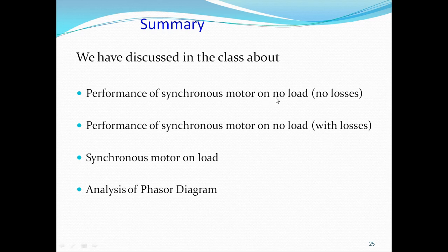In the vector diagram when the motor is on no load with no losses, both the supply voltage and the back EMF are equal and opposite to each other. When it has losses with no load, the back EMF is pulled back by an angle alpha. If we increase the load, the alpha angle increases more, which develops the new torque, sufficient to bear the new load.